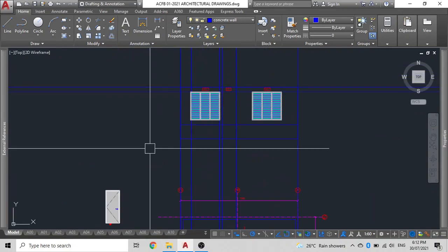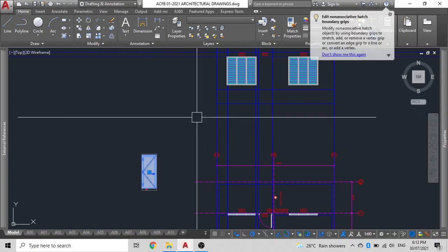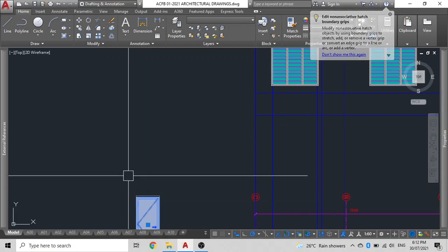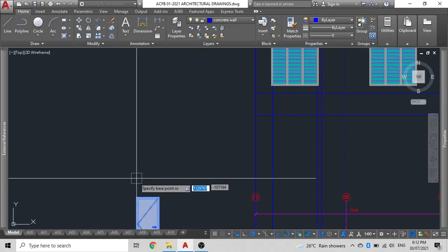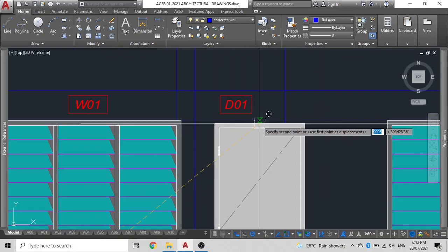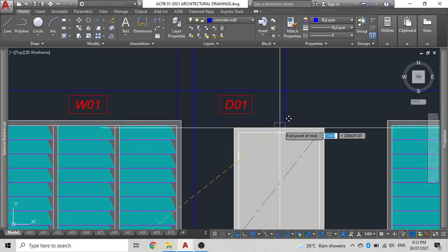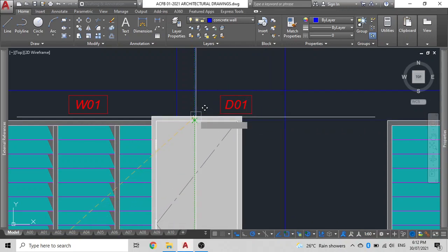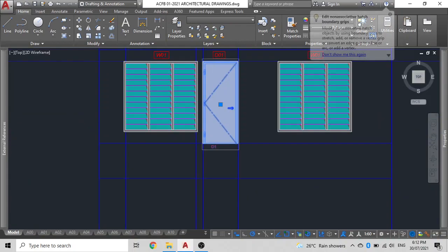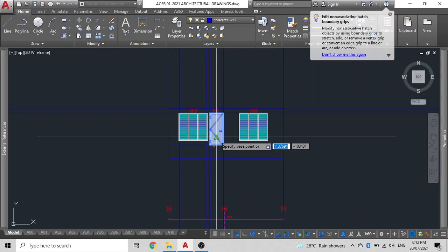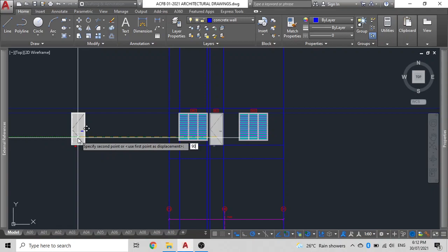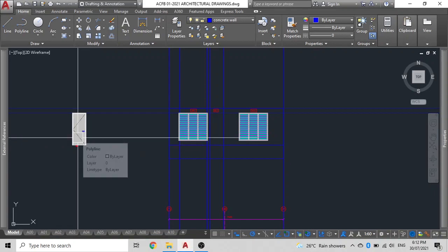You don't have to draw X lines unnecessarily. Now the next thing that we'll do is we will offset this door. We'll copy this door. Rather, we can just move it because it's one door. Find the center and just mirror to point, M2P. And paste it there like so. Then I'll move it out at a distance. I'll say 9,000 millimeters. And remember that figure because you'll be moving it back in.